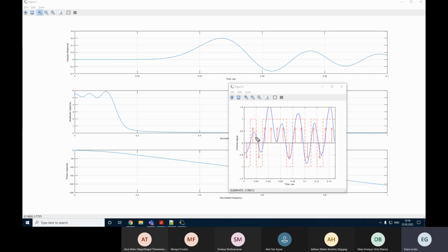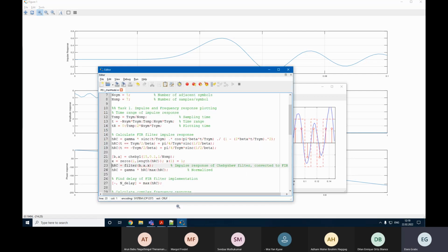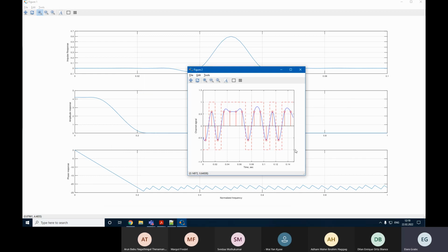How many symbols are affecting, how they are affecting, this clearly depends on the channel. Yes, so basically we'll talk more about this inter-symbol interference and how to solve it, because sadly, real channels never have this filter response that we designed for our receiver. So once again, I would return to this, our filter. This is the design of the filters we use in communication devices, receivers and transmitters. However, real channels have a completely different impulse response, and sadly, they are nowhere near what we want. For that reason, we have to design a compensating filter in the receiver that would accordingly reduce the effect of a channel. But that will be the discussion for the next time.